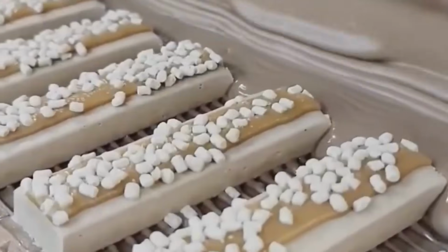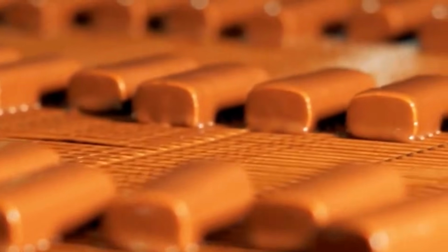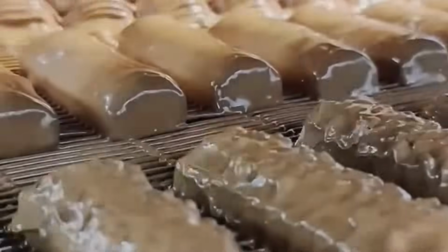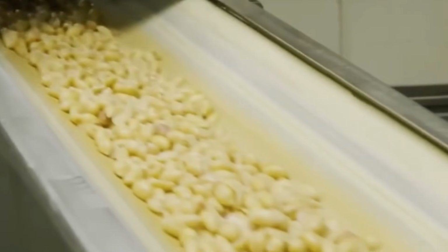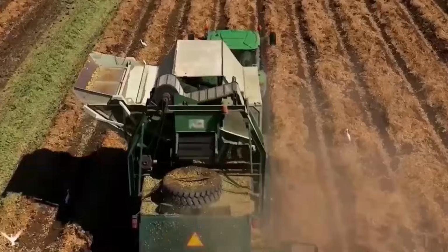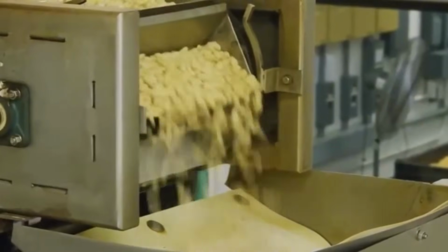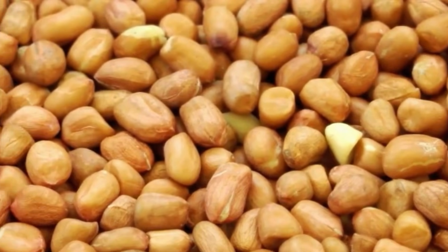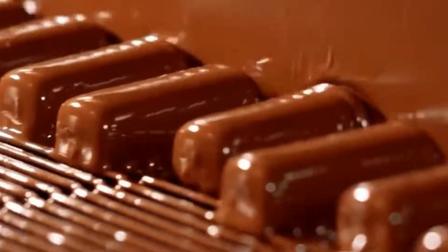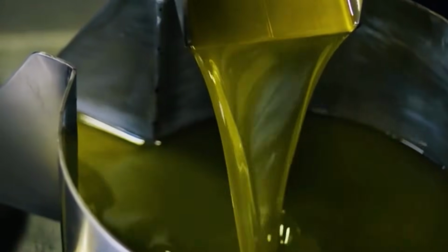Preventive maintenance schedules for all equipment are based on run hours or production cycles. Components such as chocolate pumps, depositor nozzles, cutter blades, belt rollers, and sealing jaws are inspected and replaced as needed. Maintenance activities are logged in a computerized maintenance management system, CMMS, which alerts engineering teams when parts reach predefined wear thresholds. Quality control includes hourly sampling of bars for destructive testing.